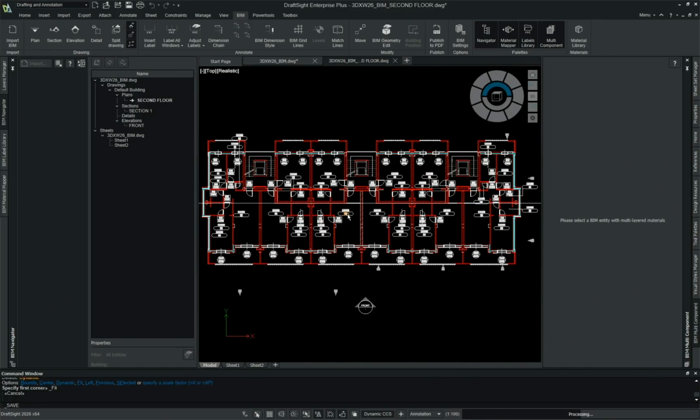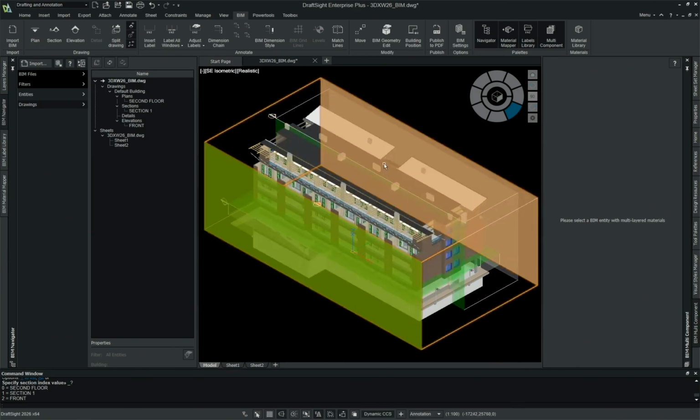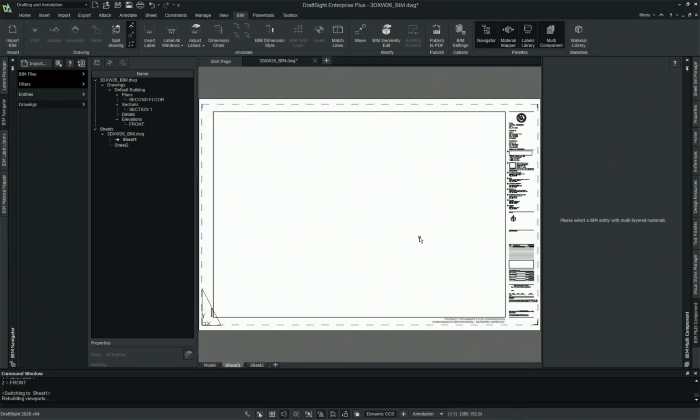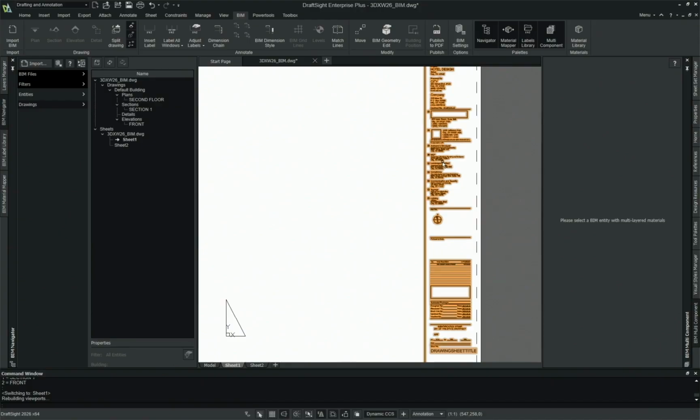What I'm going to do is go back to our drawing here and show how we set it up onto our actual sheet space to see what our deliverable drawings will look like. So here we're back in our model, or our master file. I'm going to go into our sheet space, and we have a title block. I've already set up a title block in this file.